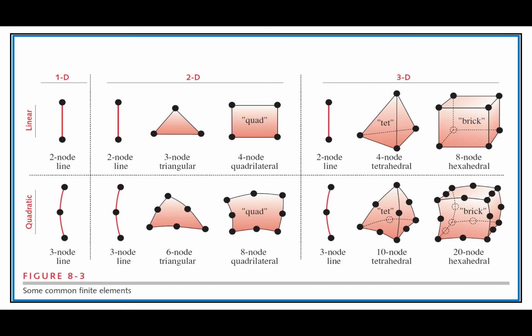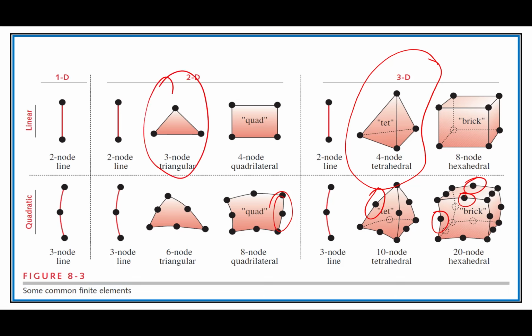This is from another book by Bob Norton, and he's just showing that. Maybe the thing I want to take away from here are these mid-side nodes that are sometimes hidden from you, sometimes they're exposed. They definitely have helped to make quality meshes. The easiest mesh to make for automated mesh generators are the triangular ones. And it used to be in the history of FEA that those were overly stiff, but they've made a better quality element in the last 20 plus years.